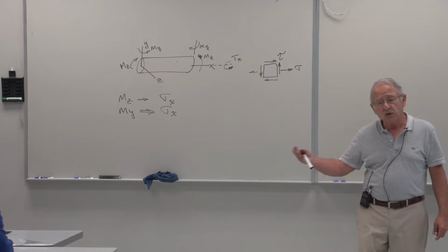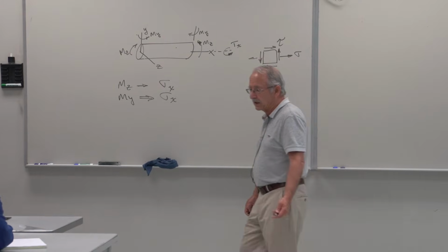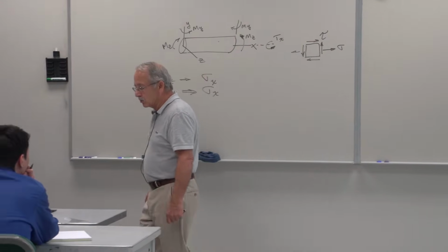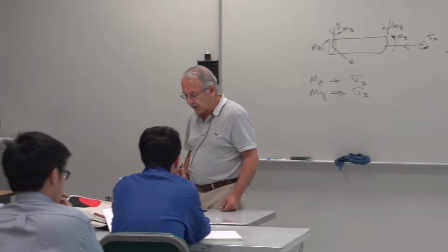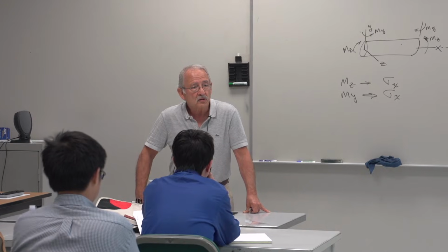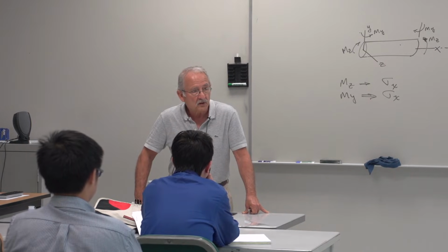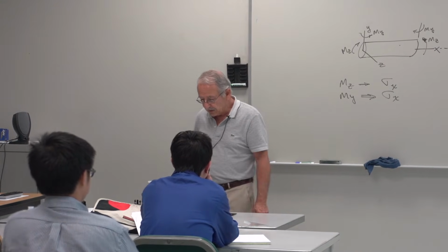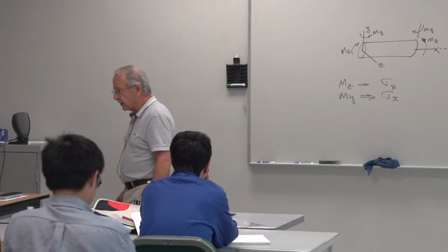That, of course, is not true if we're talking about fatigue. That is something that you need to be aware of and check the part frequently to make sure that undue cracks are not present in it. But that's what shafts are made of.